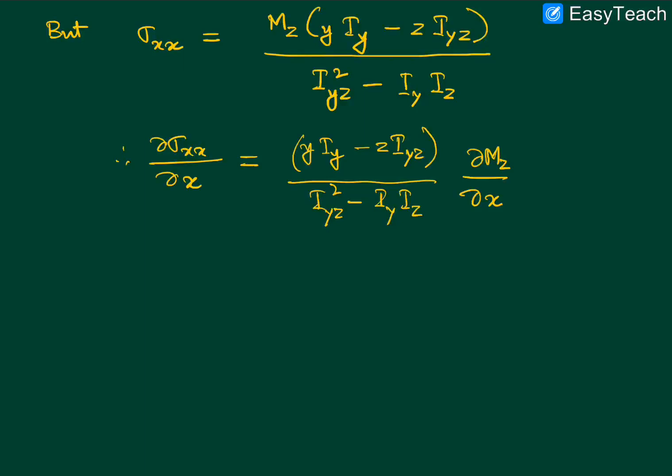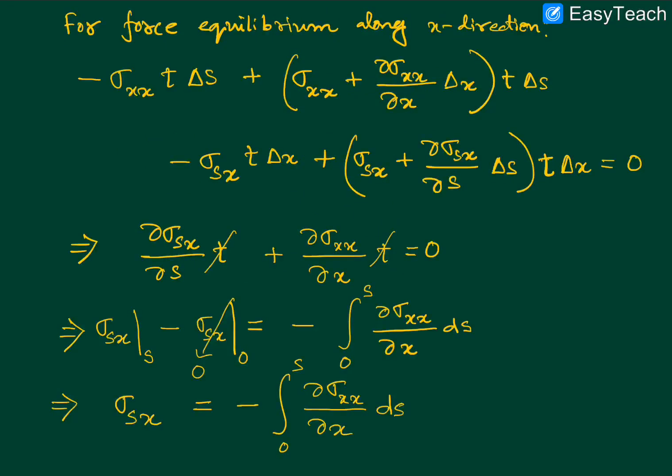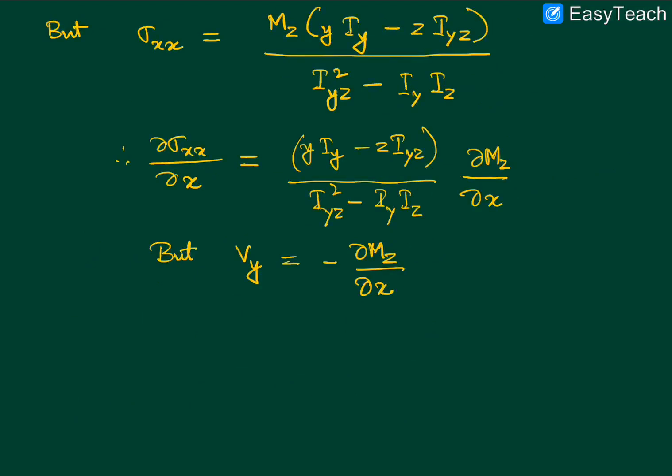Okay, but we know from our previous studies that the shear force will be related to the bending moment through this formula, so that if we quickly refer to the previous page, then the sigma sx will ultimately be expressed in terms of the shear force. So if we just substitute the expression for del sigma xx del x, what we are going to obtain is